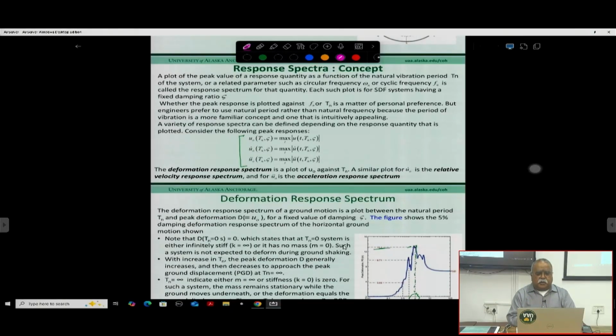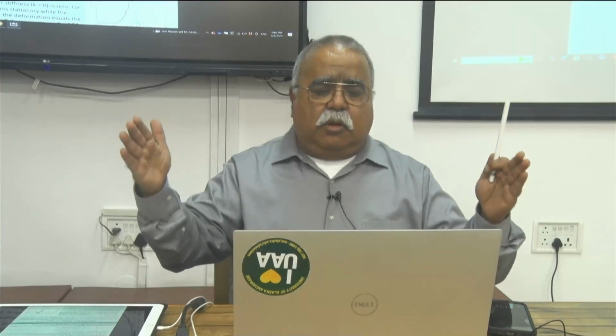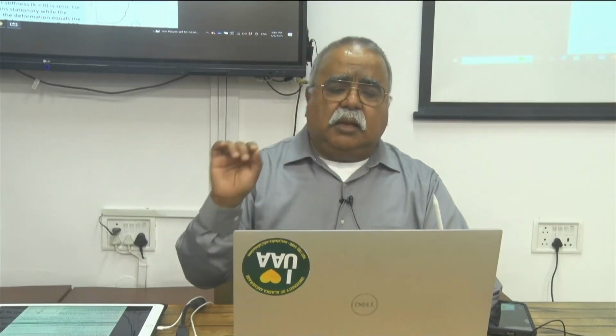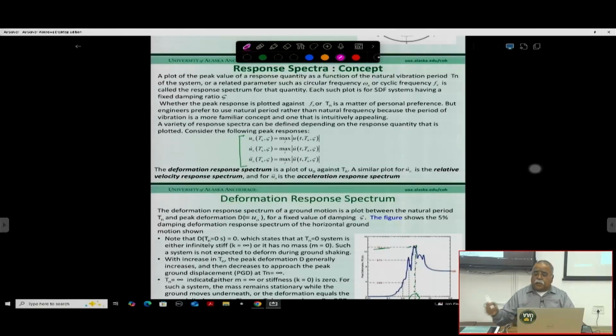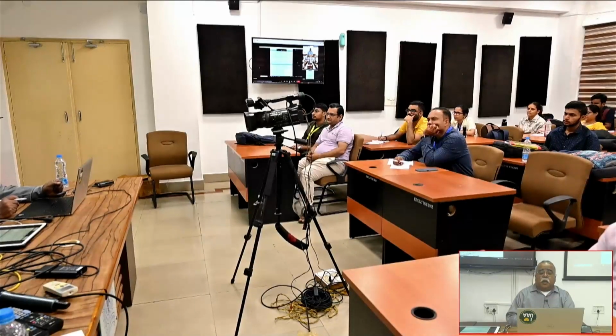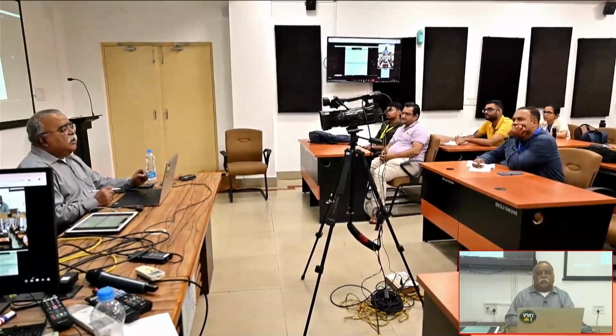So the response spectra, the concept of the response spectra, I need to explain it a little bit. As I have explained to you last time, we are calculating, over the time of the ground motion, the building response, which is called U, for the entire time, for a particular frequency and particular damping.